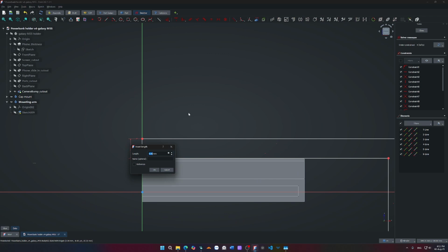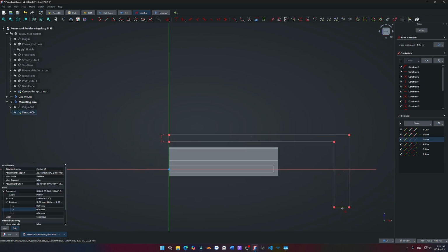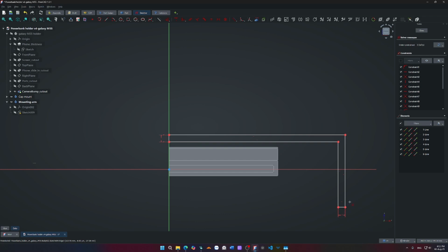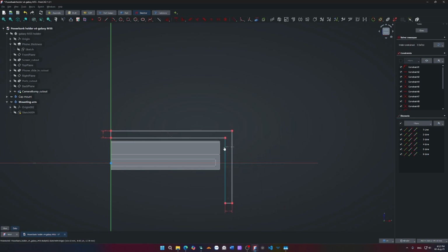Okay, I want this thing to be a bit stiff, right? So let's go for something a bit more robust than I usually do. So 5 millimeter. Same for this one over here. I usually do a 3 millimeter wall because it is very rigid for its size. I can hold up an entire 22-inch monitor with a shelf made from 3 millimeter walls.